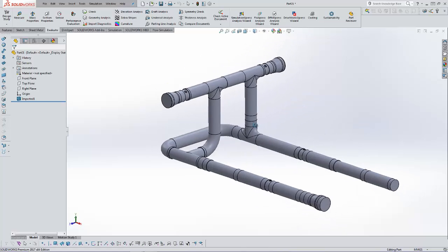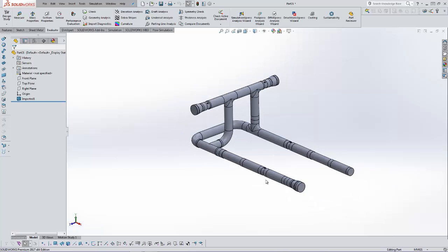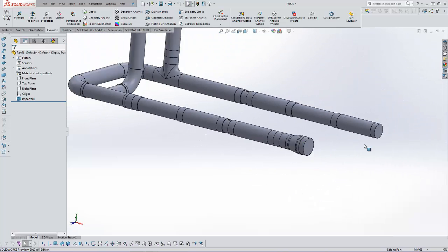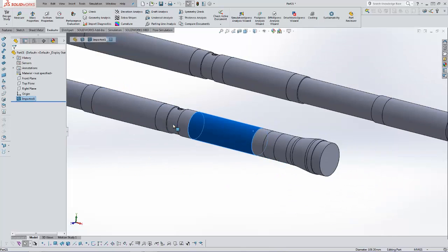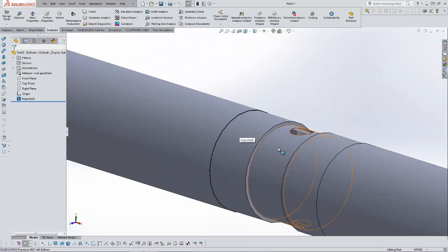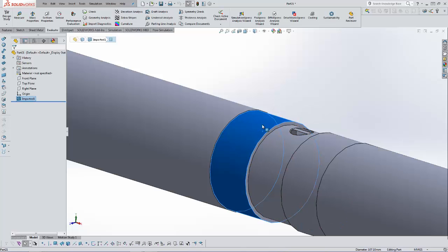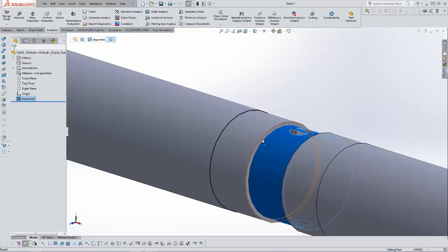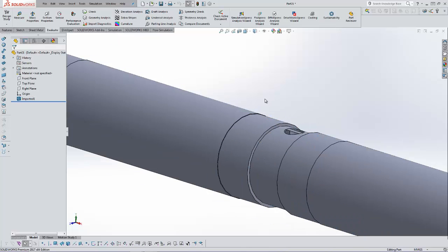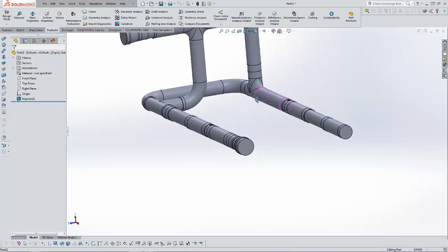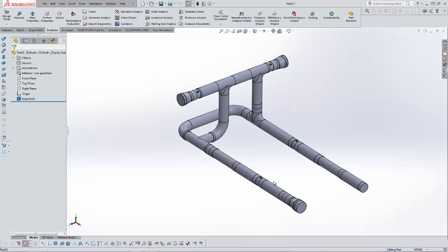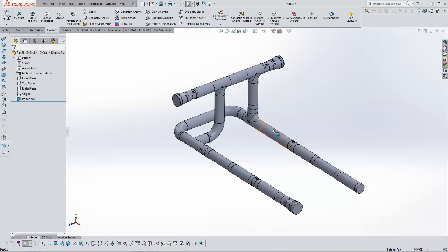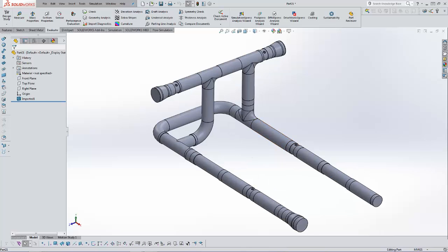It looks great, but it looks more complicated. There are so many steps from here to here, also here to here. It doesn't look so good. Steps like this will create many meshes and many different skewness meshes. It means more calculation and it's hard to find convergence. So I guess I need to do some modification of this model. Okay, wait a minute. I will modify it a little bit.